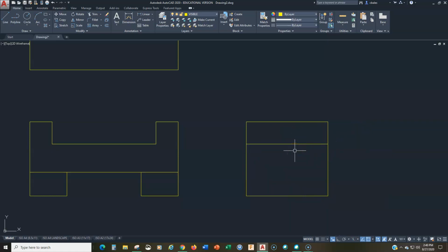Now, in fact, that line that I just drew is going to be a hidden line, so I'll come back and make that a hidden line later. This is 18, so I'm going to go 18 across here to here, and then the depth is 7, offset 7, and now we just got to clean this up. I think with a lot of drawings, cleaning up is getting rid of lines that shouldn't be there. You've got to trim them.